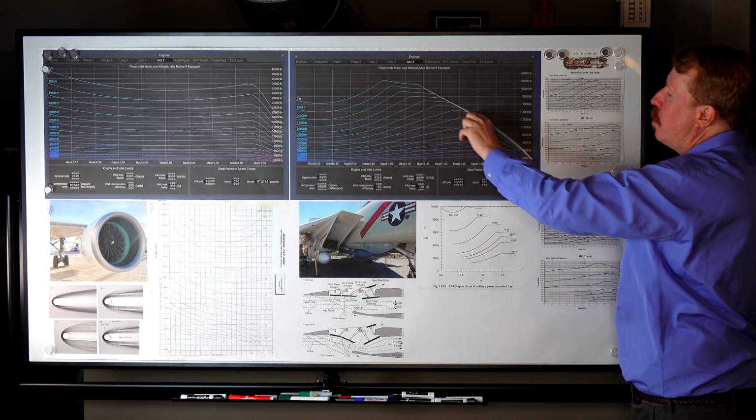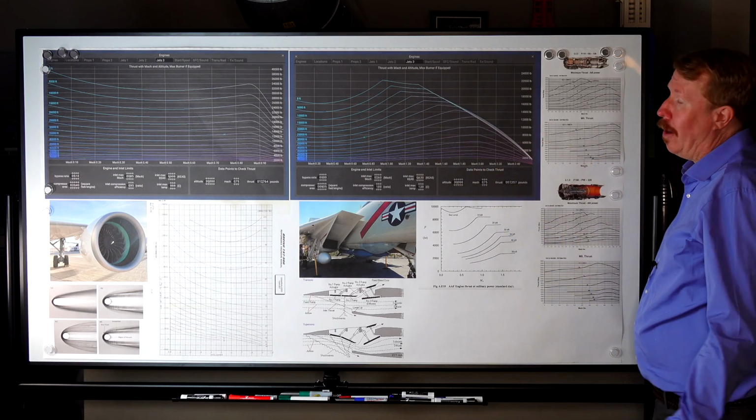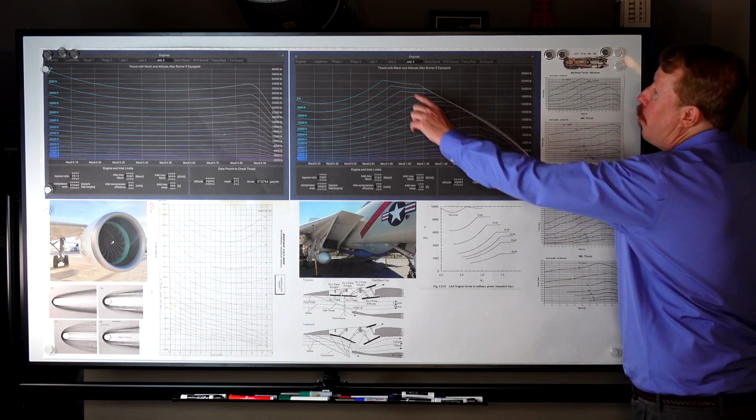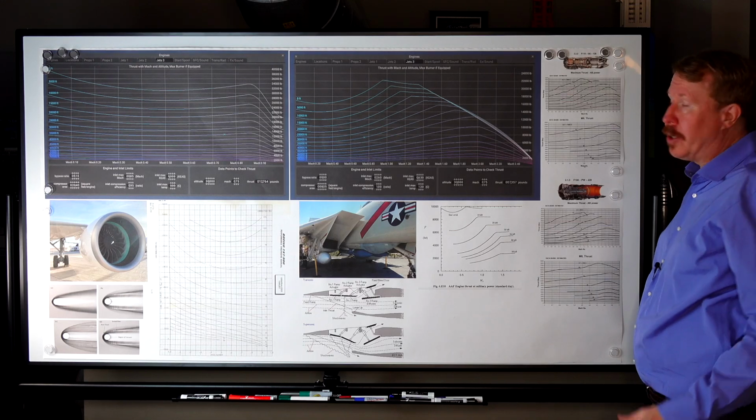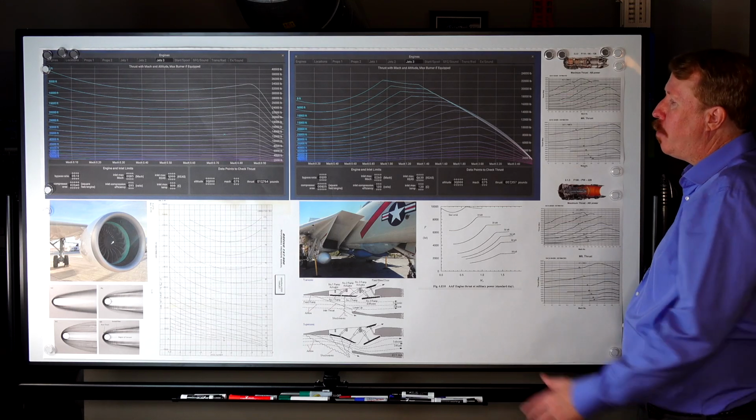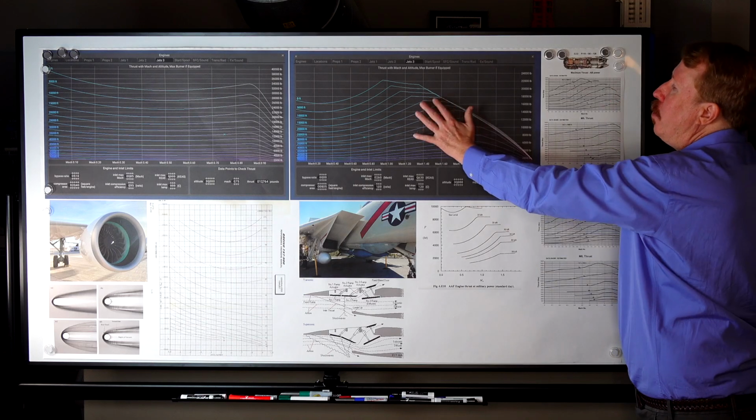But then eventually you're going to run into a temperature limit. I don't care how high you are, that temperature limit is at some point going to stop you from accelerating anymore. And so this is the thrust curve that results. It's all first principles math, and when you enter these constants in PlaneMaker, you'll be able to set these curves